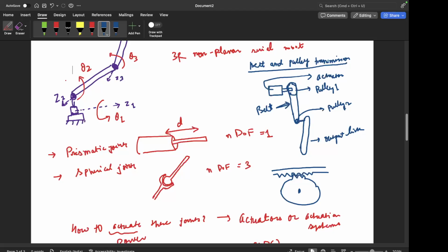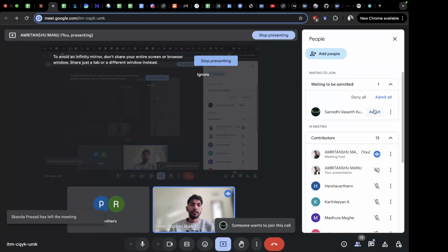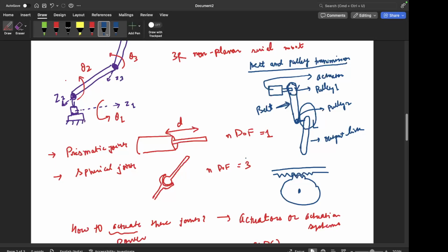So here also, if this pulley is mounted on the actuator shaft, the actuator shaft can rotate one complete revolution, and when it rotates one revolution, this would not make one revolution here, because if there is some gear ratio, then it would move accordingly, right? But this link can freely rotate in this plane, and this can rotate here freely. So there is no such loss of range of motion due to transmission, unless there are some other constraints in your system, not in general.